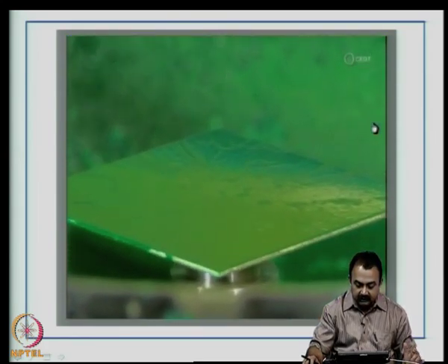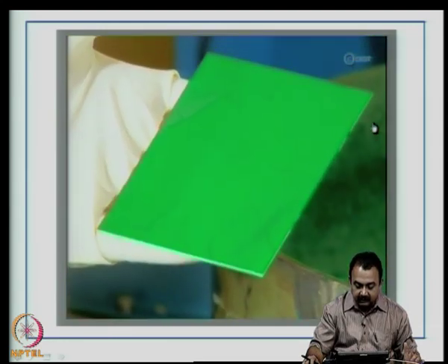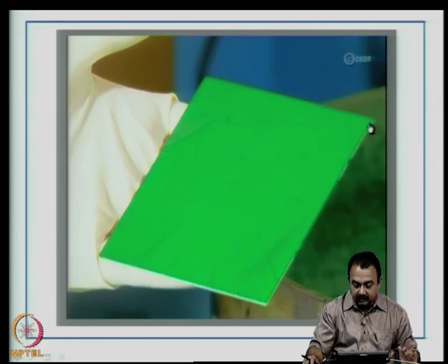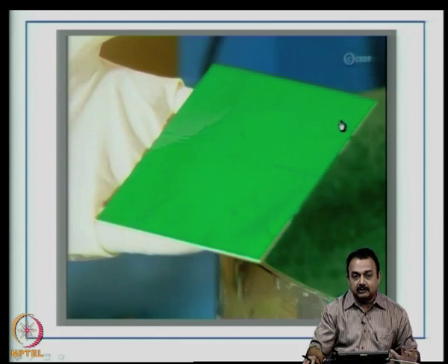So, now you can see a fairly decent spread of the material has taken place. Even then this is not 100%, because the viscosity of this particular material is very high. So, you will have a chance to work with different types of materials during the spin coating process, and the key is to obtain uniform thickness plus minus 3 microns around the entire area of the substrate.